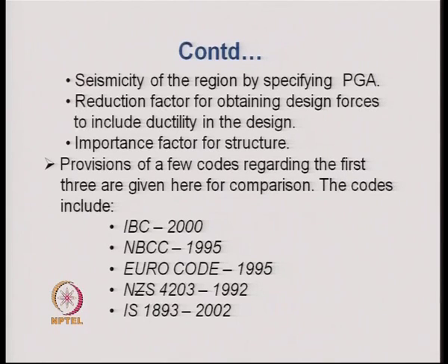When it goes into the inelastic range, we permit a certain amount of inelasticity into the design. That is, after it has yielded, we allow some kind of displacement to take place in the inelastic range.